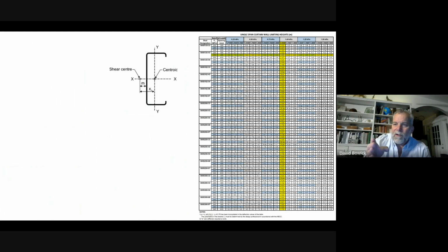And so now I've got this column, and I move down the column until I see a number that is equal to or greater than the height that I need. And so you can see that I hit 4.5 meters. That I've determined, that's my floor to floor height. And then I scroll to the left, and that tells me what my designation is. You can see that my major rows, each one of those is a stud designation.